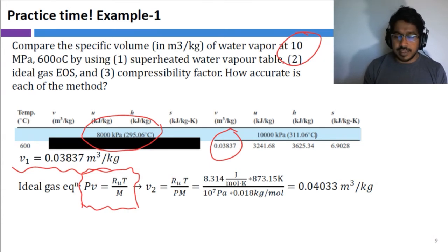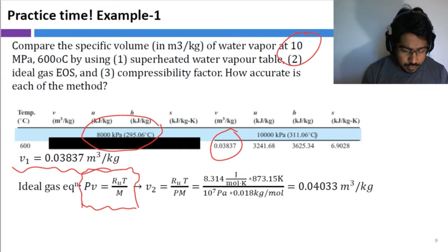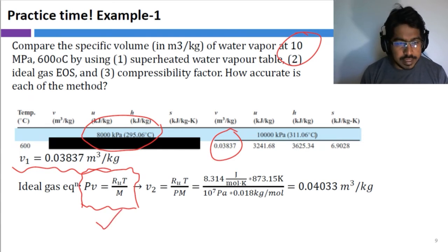Water is significantly deviant from the ideal gas behavior. That's why we are not using that. And at the same time, on another note, we have a comprehensive set of property tables for water. So whenever we have the property tables, we are not using ideal gas equation for that substance, right? So in the case of water, we are not going to use this. This is just for demonstration, to compare the values, okay? Perfect. So anybody having challenge in understanding this equation? Okay, so I see none.